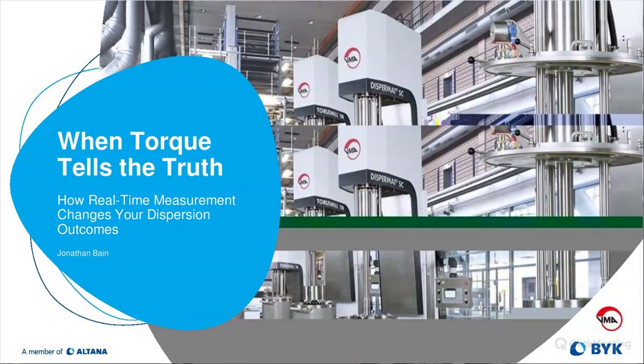We want to shorten the time that it takes to produce our materials, and we want the quality to go up. Well, in dispersion, there's no difference in that scenario. So we want to shorten our dispersion times. We want to gain real knowledge into how the materials are performing to be more productive. And the easy way to do that, we have found, is real-time torque measurement.